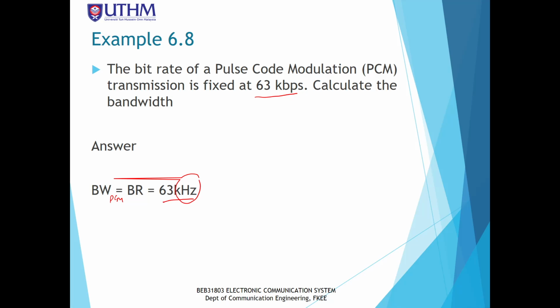Okay. Again, normally when we refer to PCM bandwidth, we normally use rectangular pulses. Okay. So that's why it is equal to the bit rate.